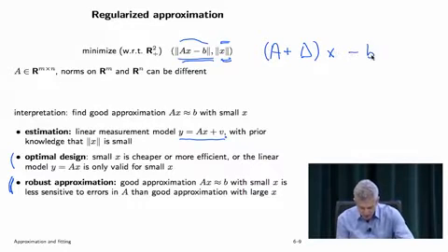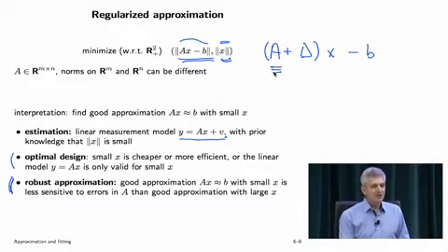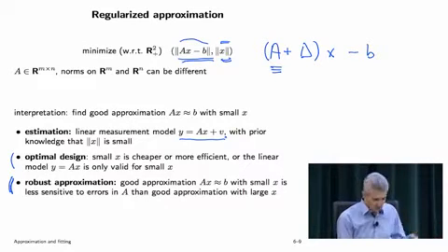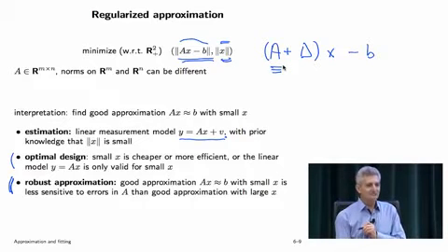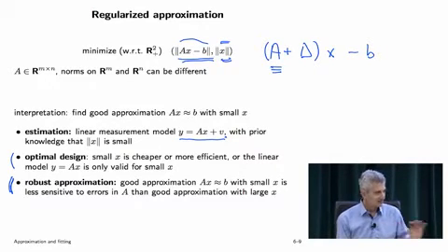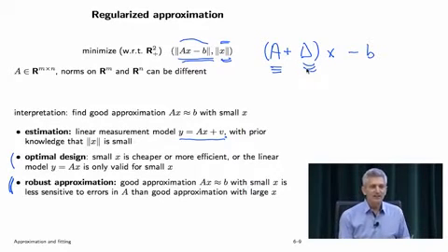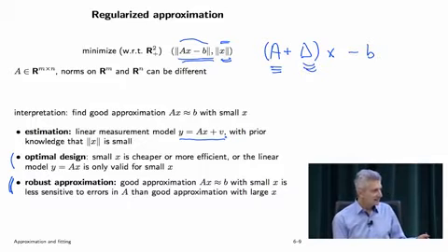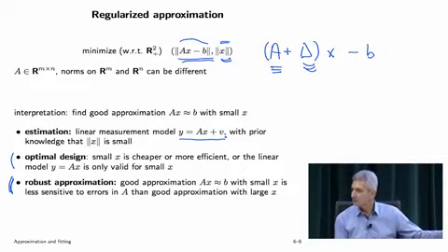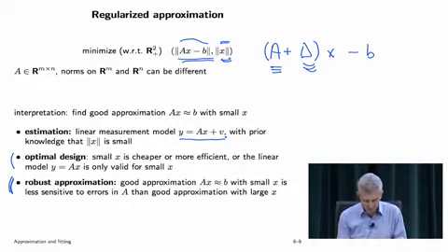What you do is you think of A as the nominal one, and delta is a matrix, presumably small, which is basically your error in A. So for an aircraft, this is the nominal model that assumes that your estimate of the mass, moment of inertia, blah blah blah, all these things are perfect, double precision perfect, right? This is basically variations due to the fact that these things are manufactured, things vary by 1%, all sorts of things happen. That's what the delta is here.